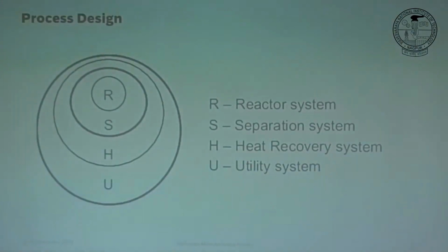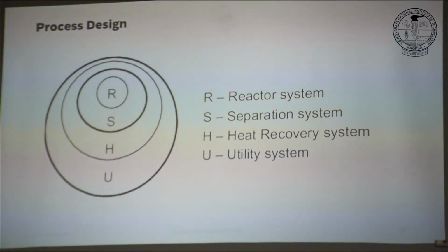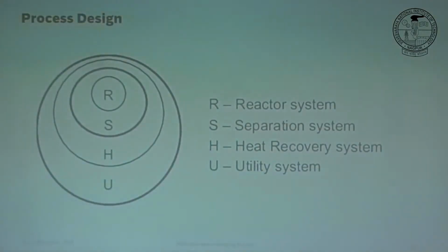So that's the onion model of process design I was talking about. You guys are familiar. So we start with the reactor system, and we already saw that we do not have full conversion of methane. That means we have some unconverted methane. On top, we have some byproducts like carbon monoxide here. Since we supplied excess steam, we also have unreacted steam left. So what comes out from this reactor or reactive system would be hydrogen, unconverted methane, CO, water or steam, and any other byproduct.